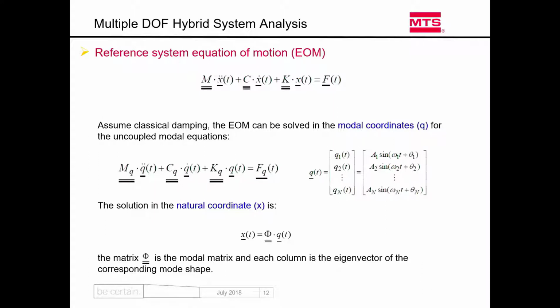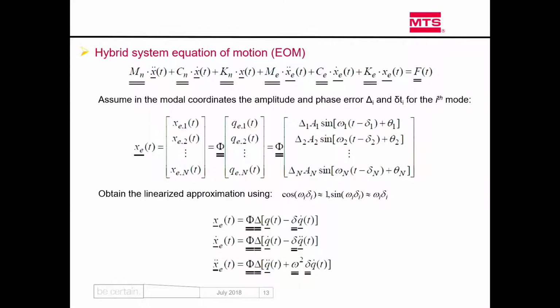Go to multiple degree of freedom, everything becomes matrix form. But the same thing, you can solve using the modal coordinate system, and that's just structural dynamics, right? You convert from the natural coordinate system X into the modal coordinate system. And then again, we do the same technique.